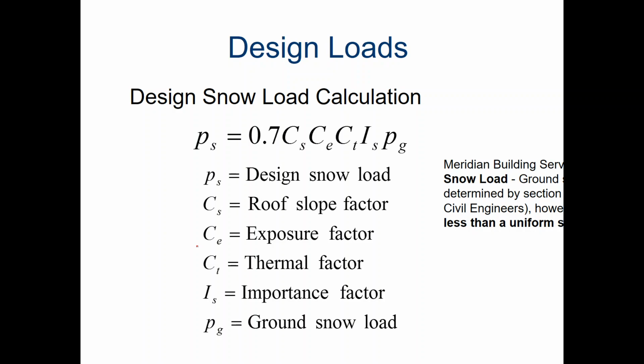So when you are calculating the snow load, what you're looking for is this magic number PS, or the design snow load. So we have this formula for your design snow load, and it involves all of these things underneath. Let me talk a little bit about what those things underneath all involve.